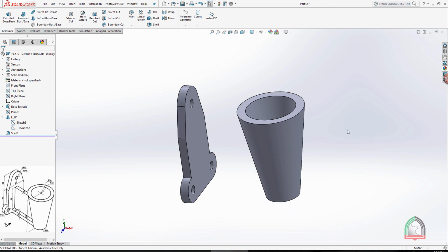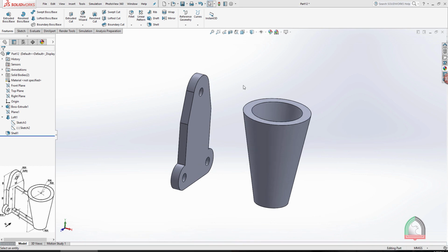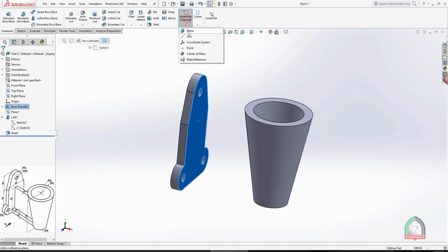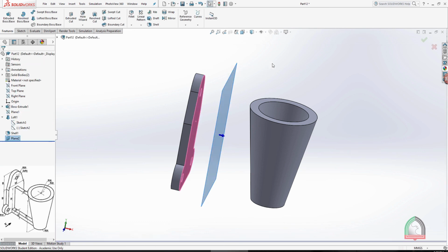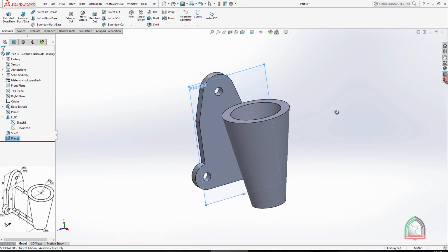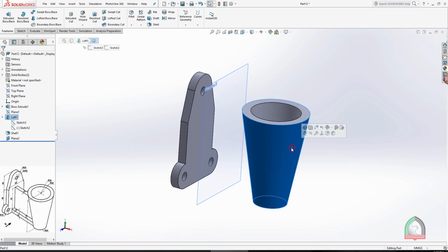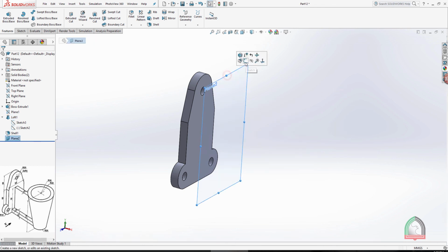So all the things will be updated now. See, here it is. Now only one part is pending, that is the mid portion. Now I need to create a plane in between these two. So for that purpose I am selecting, see, I want to make it in between, so I am reducing the value here. Okay, it's in between, no need to make it in the exact middle or something. So I have plane here, but at the time when I'm trying to draw something over here, you can see that this is actually obstructing my vision. In order to avoid that, I click on this one, go for hide. See, now the plane is directly available.